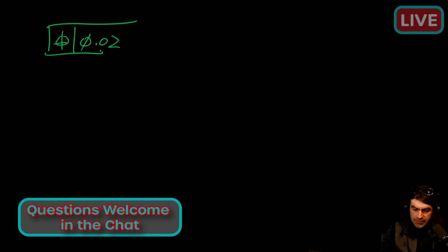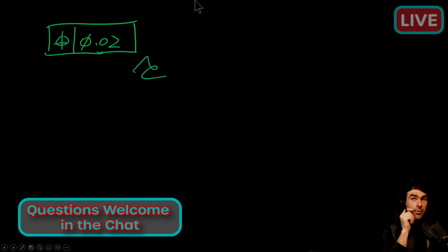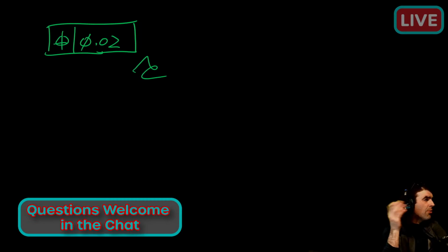So the question is basically, what about position with no datum references? Like, what's going on with that? They're not super specific about what situation they're seeing it in. I can tell you this: in ASME, you can use position only with features of size and bounded features, which is like an enclosed feature of size, but irregular, I guess.